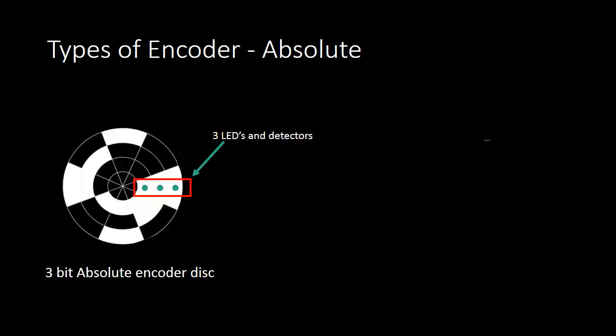The number of slots on the disc directly affects the resolution. If there are too many lines, or slots, this will decrease the light that can pass through because the slots are smaller, and also the signal strength decreases as the speed increases.